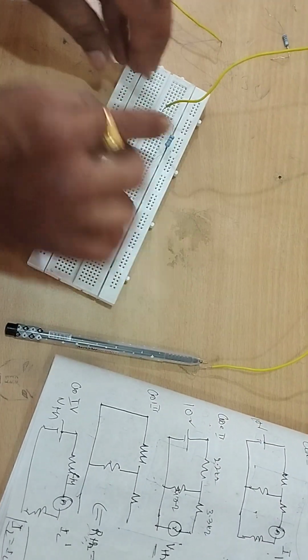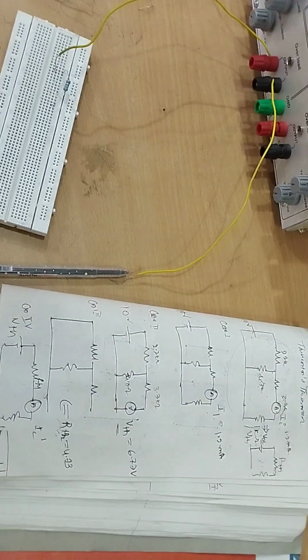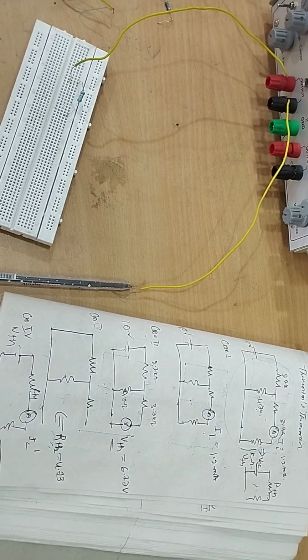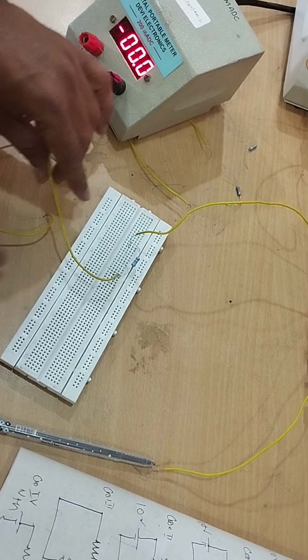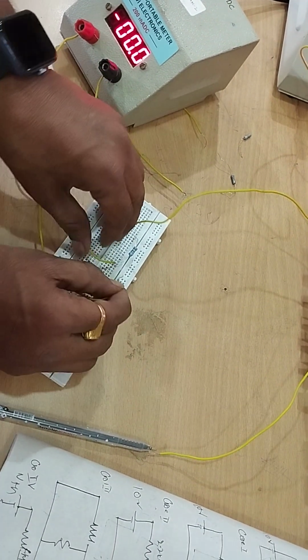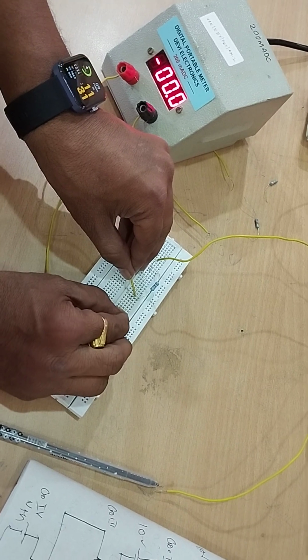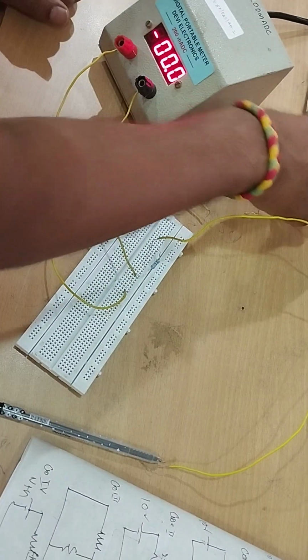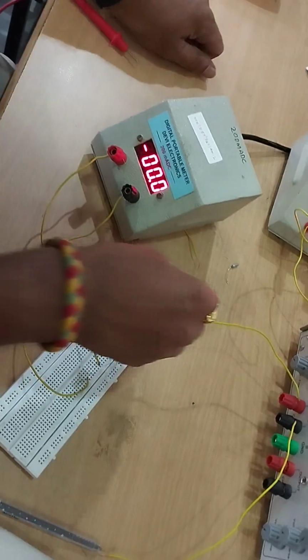So the voltage positive is connected here as shown in the circuit diagram, and the ammeter. We have to take the ammeter and connect it to the R Thevenin end, and we'll make a gap between the R Thevenin end and the positive terminal of the ammeter. The negative I have placed here, and now I'll take the load resistor which is to be connected in the circuit.